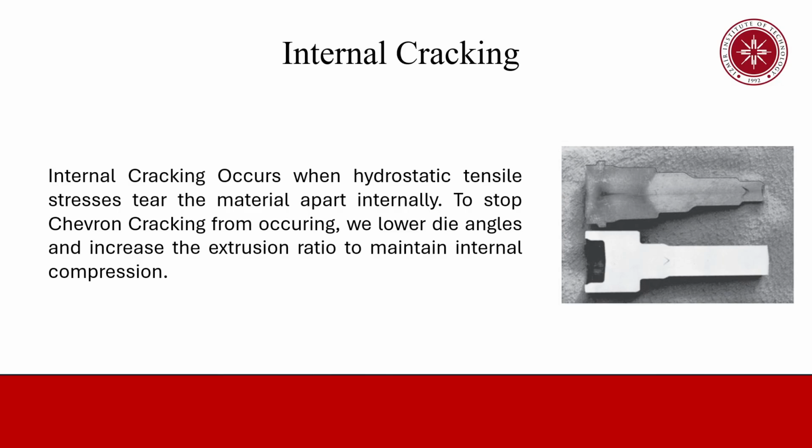It also increases if the material has a higher amount of impurities. But it might seem kind of counterintuitive: the tendency decreases if we increase the extrusion ratio and the friction. Well, you're going to say that increasing the friction actually makes the outside crack more. Well, yes. As engineers, it is our job to find the balance between these two values and optimize our friction values.